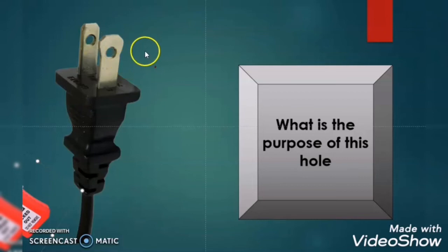Now let us try to find some other more interesting facts related to electrical plugs. In some equipment plugs, you will find holes in the plug pins. What is the reason behind this hole in the equipment plugs? The reason is safety. Suppose this equipment which is connected with this plug needs maintenance, and this plug is far from that equipment, then you will unplug it and start the maintenance on that equipment. But if someone comes and plugs it again into the power source, then the person who is doing the maintenance on that equipment will get shocked.